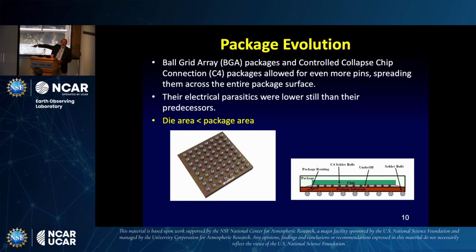With the solder bumps on the bare die, the solder bumps have to touch the surface and I have to melt it just right. I have to heat it just right for it to fuse with the printed circuit board. So that's something in-house in my lab at A&M I simply couldn't do, because if I overdo it, they'll all short. If I underdo it, they don't get a good connection.